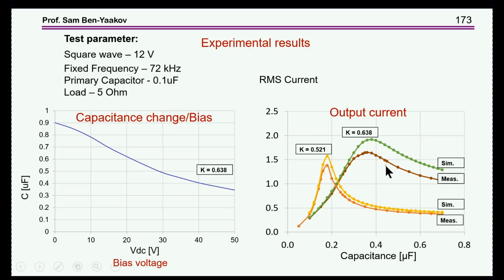Now, the difference between these two is the simulation and measured value, and the difference is explained by the fact that we have not accounted for all the losses in the circuit, parasitic resistances and things like that. So there's a distance, but the peak values are the same. So it looks like we can actually have a good simulation by trimming of the actual operation of the circuit.